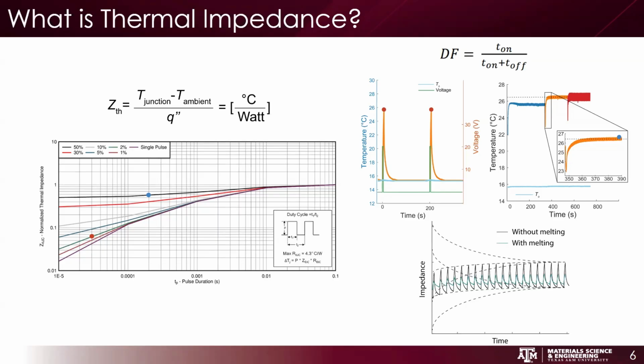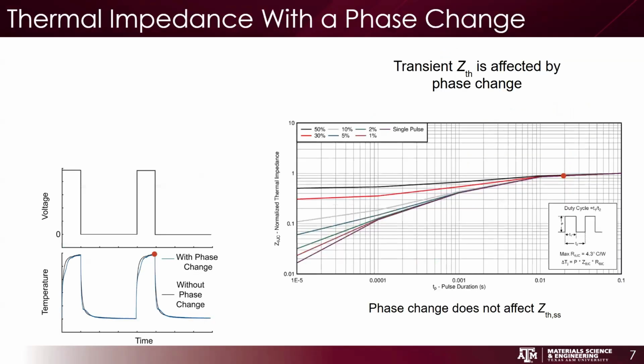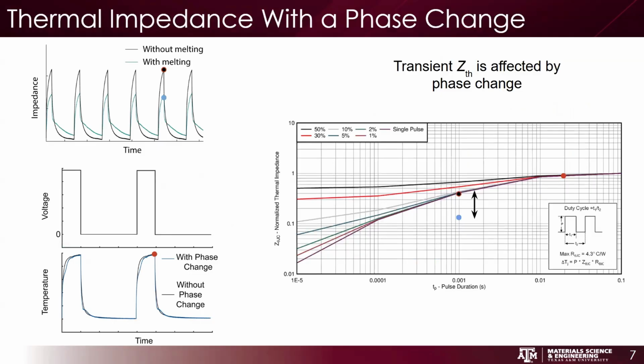And this graph is the thing that would model that. Irrespective of your initial temperature of the system, if you have identical heat loads being pulsed onto it, it's going to reach some quasi-steady state equilibrium maximum temperature. Under these transient thermal loads, if we look at this duty factor, it would be an on time, then some oscillation. And if you're in a temperature range that's unlocking or using the latent heat of the system, you can have a junction temperature suppression.